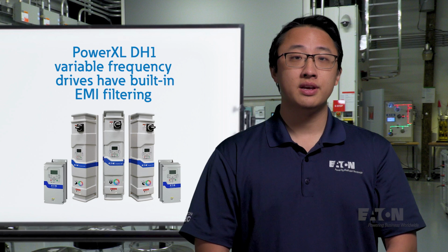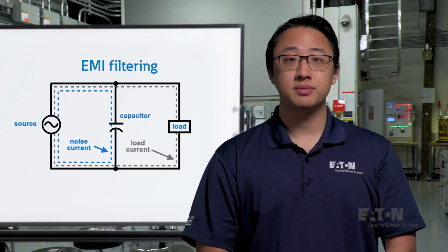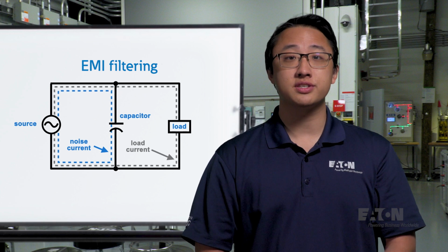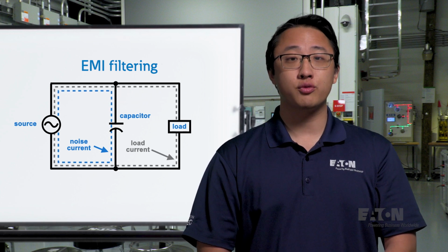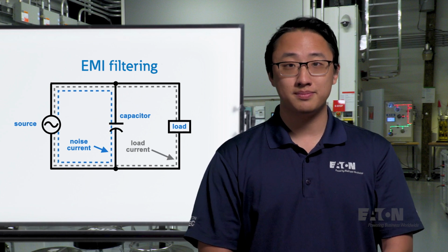Similarly, a lot of electronics today will have EMI filtering modules for sensitive electronics, like on these variable frequency drives. These filters clean up noise by putting capacitors in parallel with the device. Higher frequency currents will see this as a path of lower impedance and therefore separate from the main signal, cleaning it up and ensuring reliable operation.